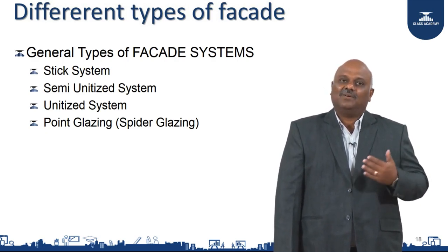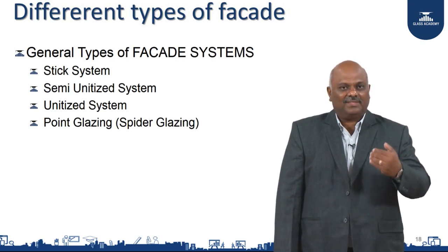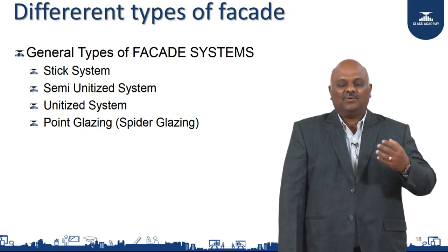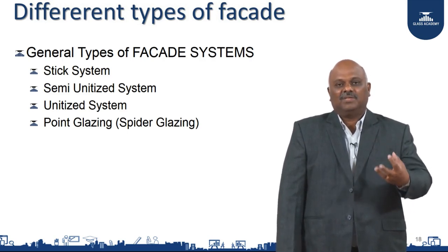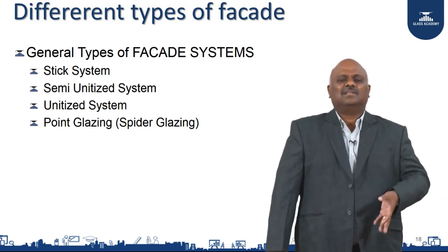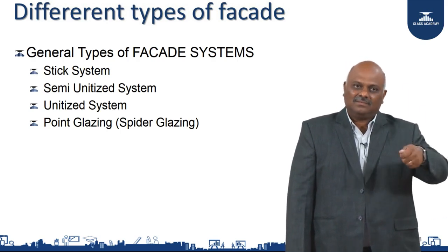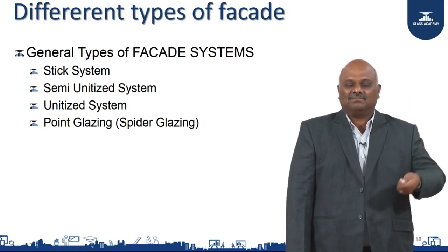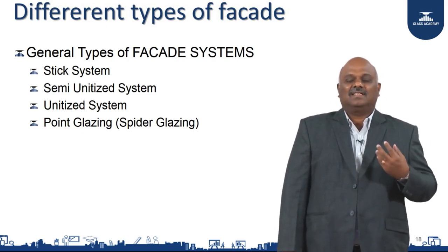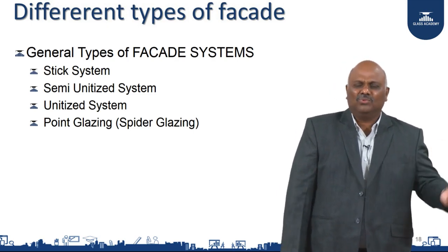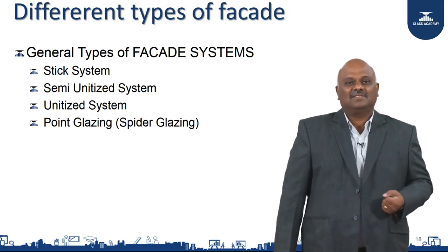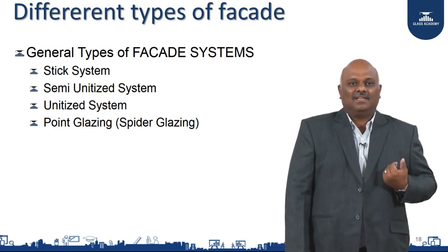So people thought, how am I going to go forward? They started to understand how to bring a little more of the work into the factory, where they started getting a lot of quality. For example, I have to install 1,000 glasses at site by fixing each piece by hand. Impossible nowadays. Also, the stick system doesn't move, expand or contract, so even though the design is there, there are a lot of limitations. Then the invention went to a semi-unitized system.